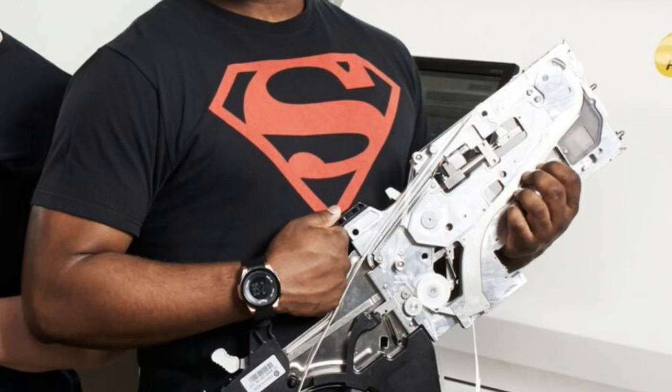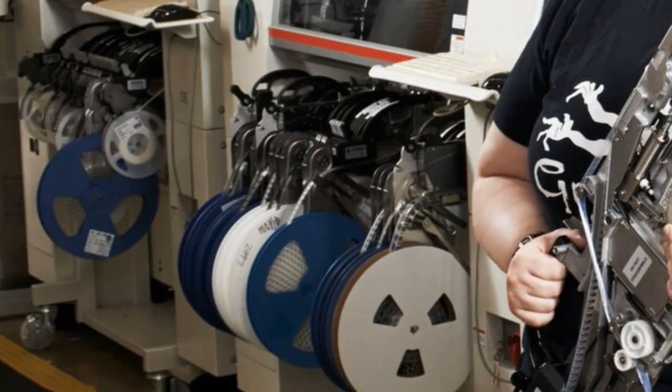Yeah, and I'll zoom over to the reels, so you see he's holding one of the feeders that hold the reels. These are the feeders that plug in. And yeah, so if you can get those parts on there. Electret microphones can't go through a reflow oven, so it's a separate step, and you have to consider it. Again, just because a part is low cost when you spec it doesn't mean it's going to be low cost when you consider the complete design.